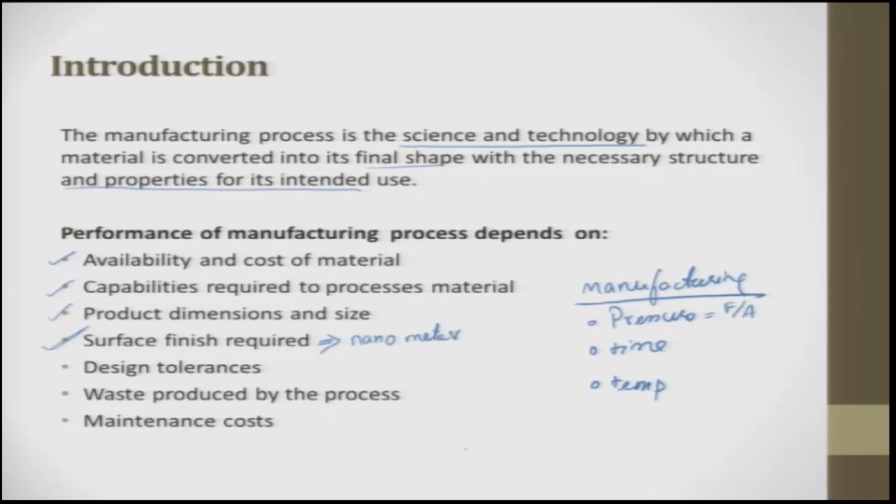So, what is surface finish? If you take the surface of a shaft and look at a zoomed-in place at this point, you will have undulations on the surface, something like this. When you mate it with a bolt, or with another contacting surface, the contacting surface will sit on these peaks. These peaks over a period of time get destroyed, and they fall in between the two mating surfaces. In the beginning, the load bearing area will be very less if you have a rough surface.